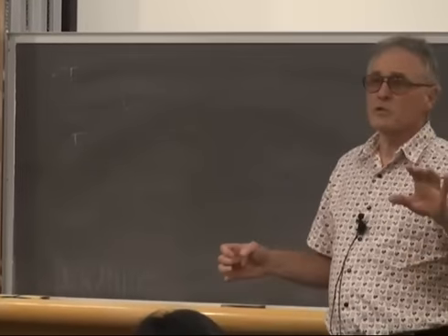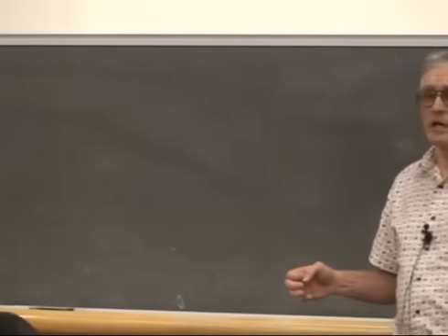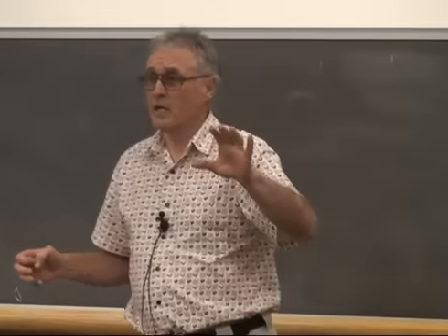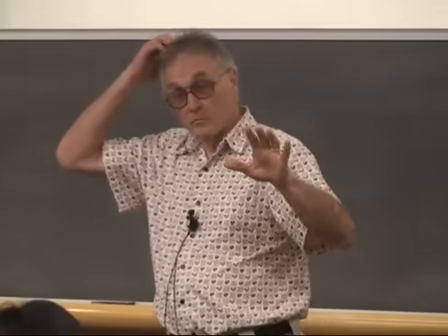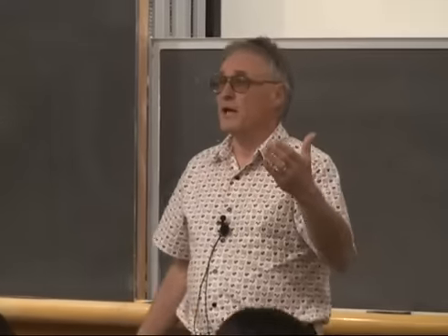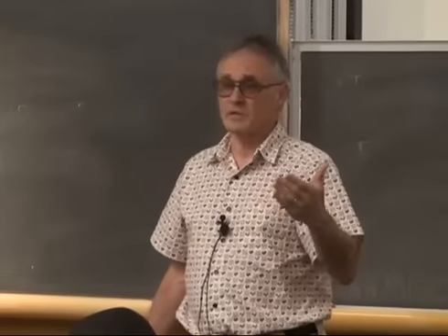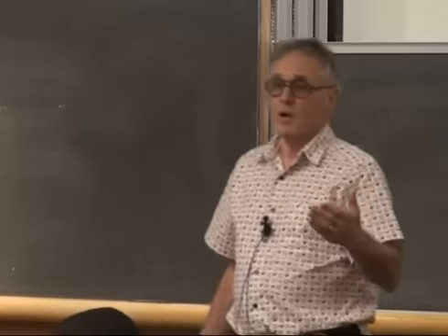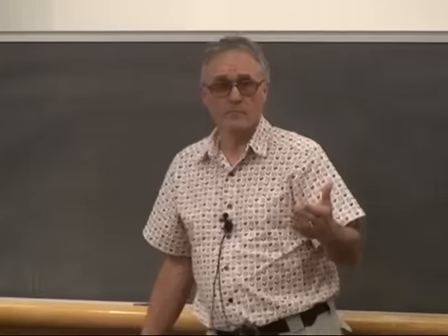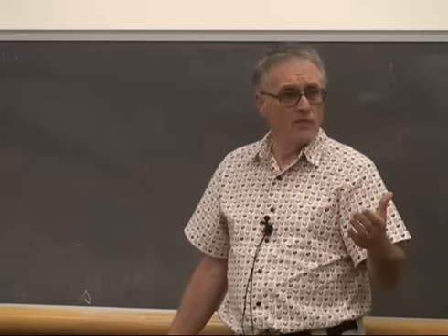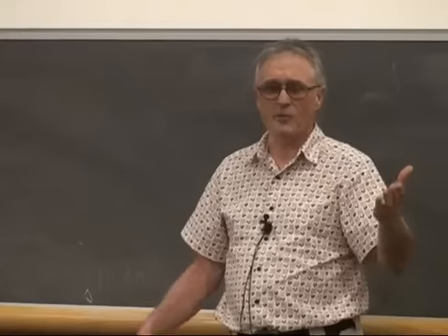Basically, we want you to justify how you're going to set up the direct digital synthesis to meet the DTMF guidelines, DTMF specs, and to justify it using knowledge from 2200. Justify it using signal processing. For instance, the highest frequency you have to generate is, what is it? 1477. I thought it was 1600, but 1477.